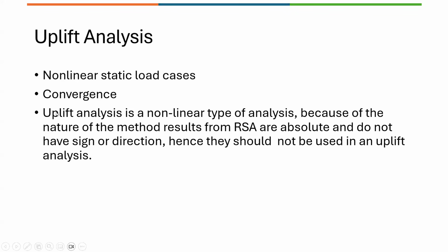And uplift analysis is a nonlinear type, right? So the response spectrum analysis, because of its nature of the method, its results cannot be used here because it has lost its sign and direction. So they should not be used in the uplift analysis.